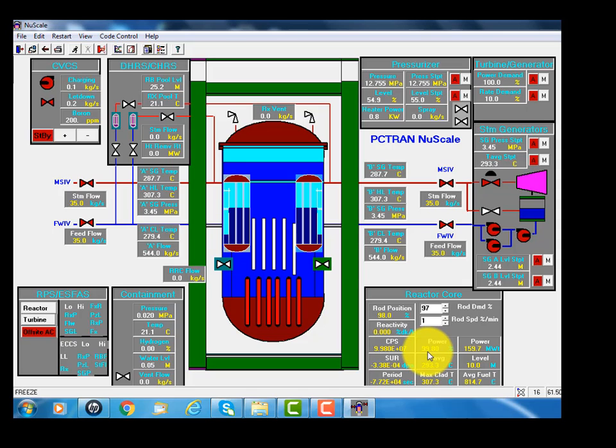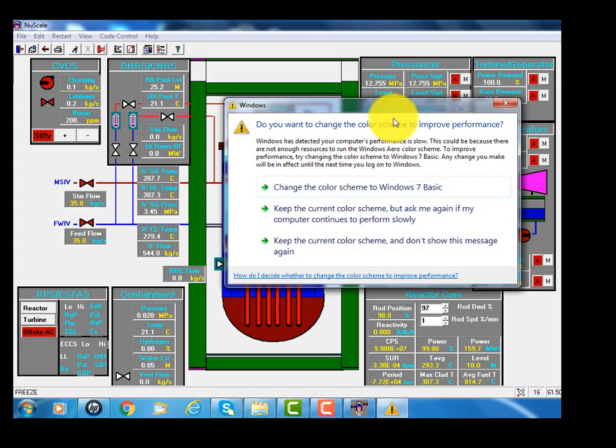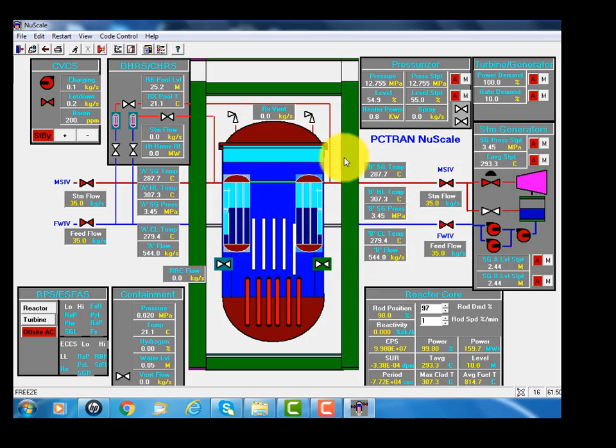And there's a very sophisticated control system and a pressurizer, and there are heaters and a spray. If the pressure is too high, the spray will turn on. If the pressure is low, the heater will turn on. And the other control of the steam generator feed water and steam pressure keeps the chain reaction balanced.